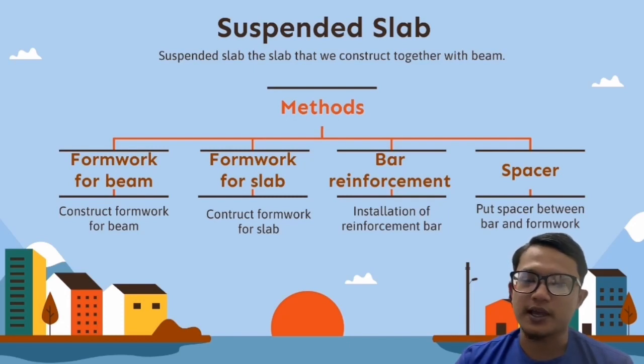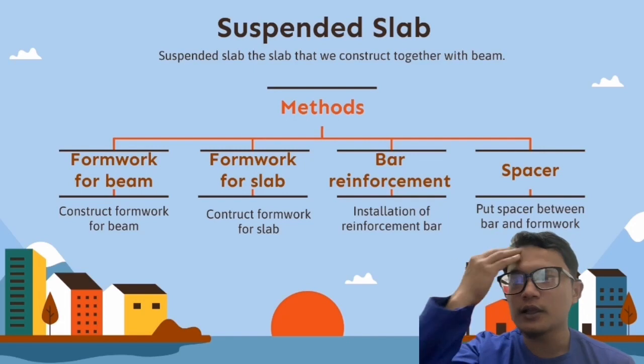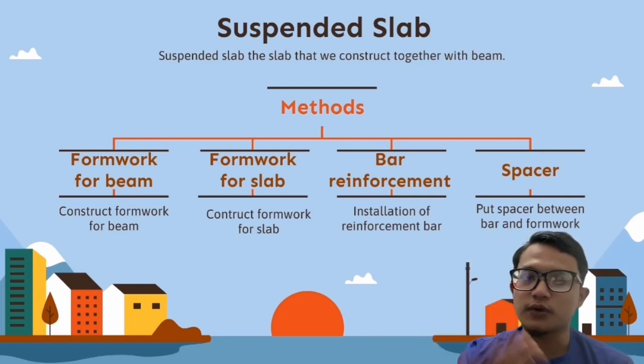The side formwork must be higher than the other one, and the middle of the beam is the same as the other one. And then you must do a formwork for the slab and make enough support. If not, you can have scaffolding underneath to cover and support enough under the plywood, under the soffit.